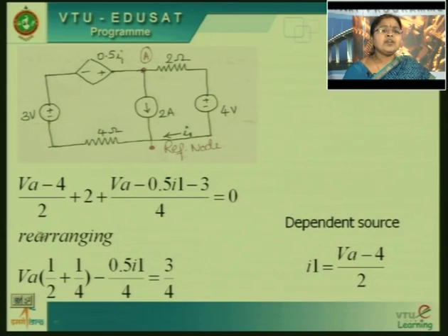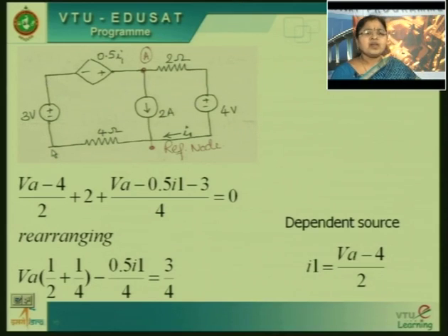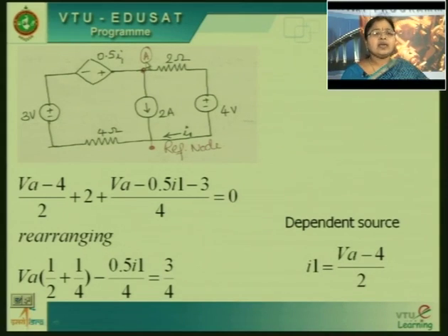Whenever you have elements connected in series, you do not need to take the in-between points as separate nodes. As per the definition, when 2 or more elements are connected, you can call it a node. But because they are all connected in series, you do not need to consider this point as a separate node. So, all these 3 are connected in series, and we will make this one independent node. I have named it A, because the current flowing through this branch is already mentioned as I1. So, instead of naming this node 1, it is better to name it A.